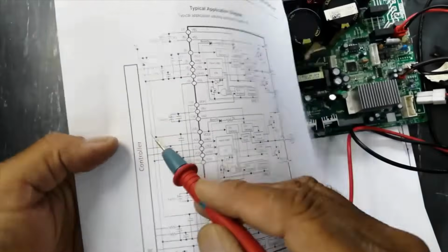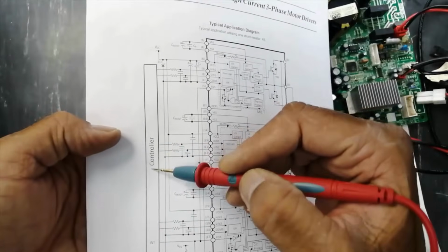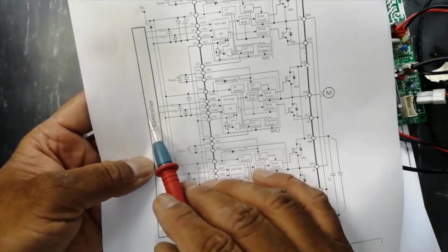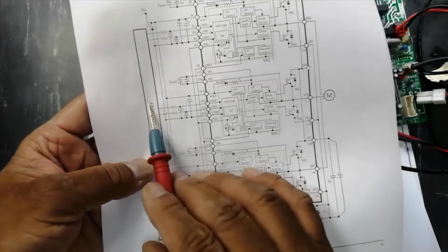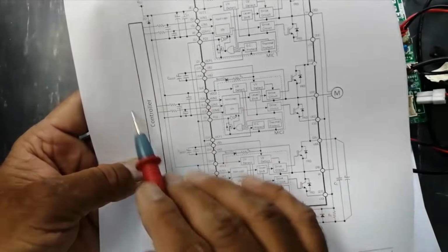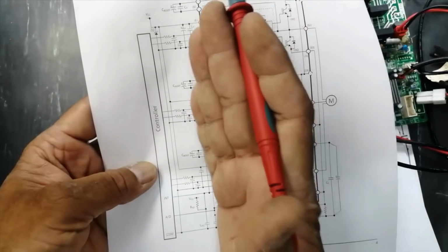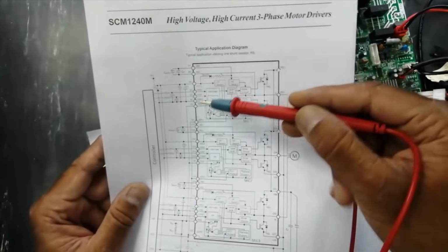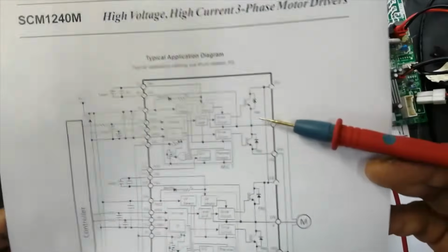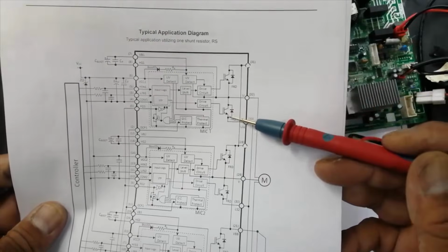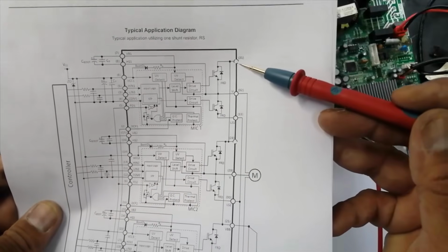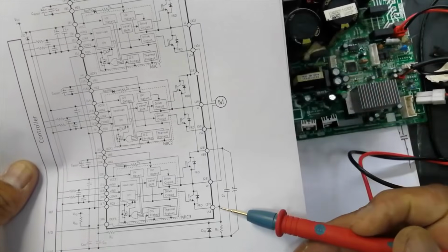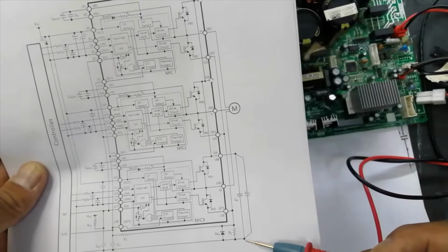So it needs a controller that will generate high frequency or variable frequency, and it will drive through a line driver, and it will give the switching voltage to these pins, high drive, low drive. So here it has a built-in high FET, low FET. At pin 31 it takes positive voltage, and at this pin it receives negative voltage.